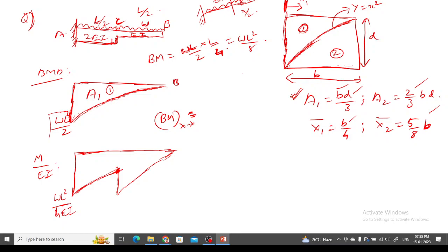Okay, sir. And the other person who asked a doubt, is it clear? So the bending moment at x will be W x into x by 2, which is W x square by 2. And here at x, what you will put is L by 2, right? Since I am taking from this direction. So it will be W into L by 2 the whole square divided by 2. It will be WL square by 8, as another person pointed out. This is the bending moment at section C.